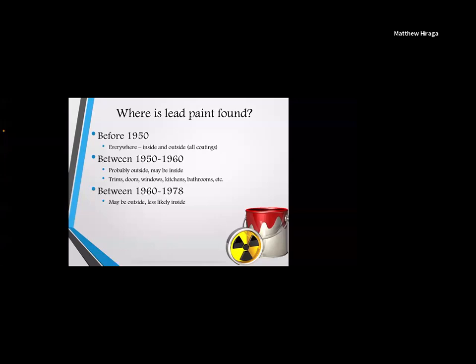There is no exact science to this. If it sat on the shelf at your local Sherwin-Williams for 10 years and you decided to buy it because it was on sale and discounted, you could have painted it after any specific time. So this isn't a guarantee. It should still be tested prior to disturbing. And then that's going to give you an idea of how you should handle it. Do I need to set up containments? Do I need to use personal protective equipment? And then it may affect even how you dispose of the materials.